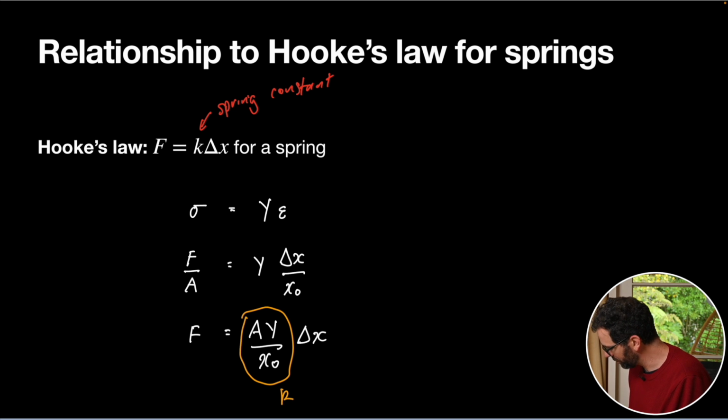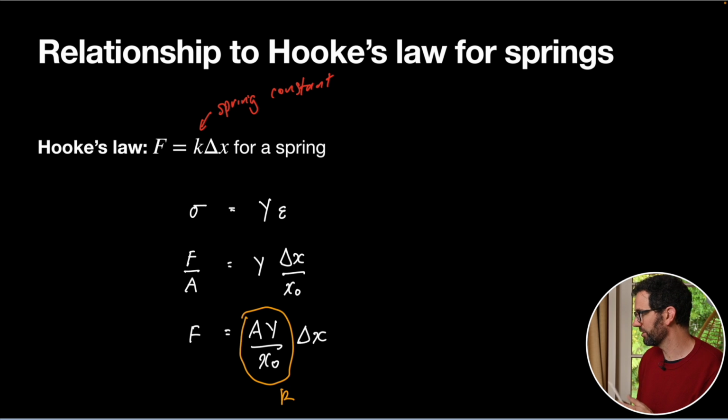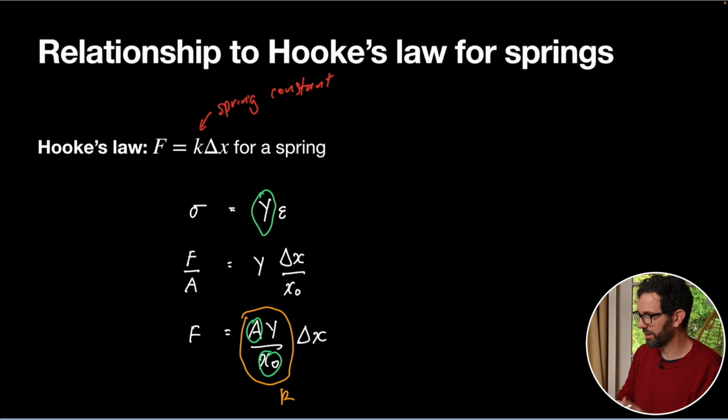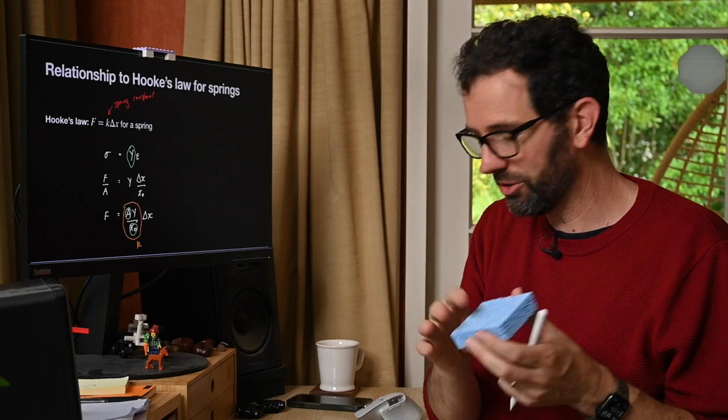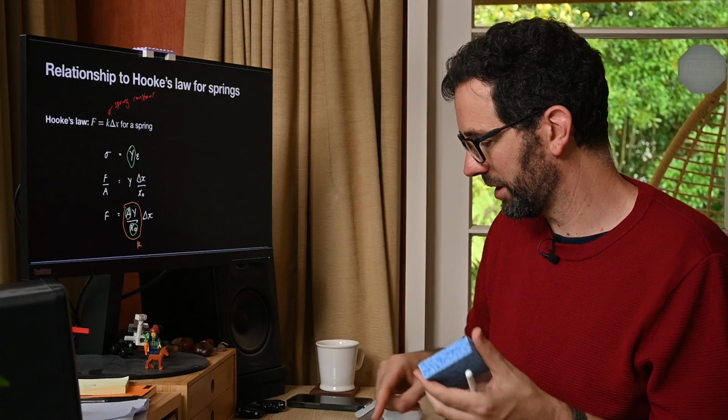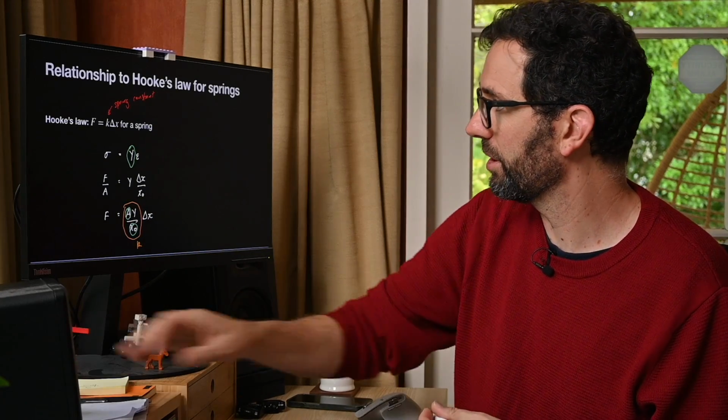So I can turn it back into an equation relating the compression and the force, and you can see that what that's done is basically I've just included the dimensions of my substance, and now I have an equation relating force and compression. But the nice thing is this Young's modulus was a property of, in my case, sponge. So if you gave me a sponge of a certain set of dimensions, I could work out this spring constant, if you like, by plugging them into that relationship there.